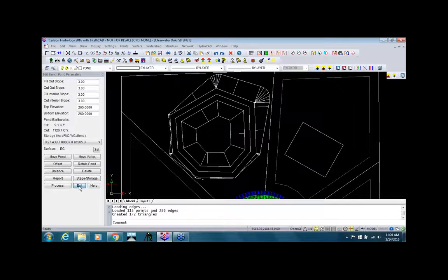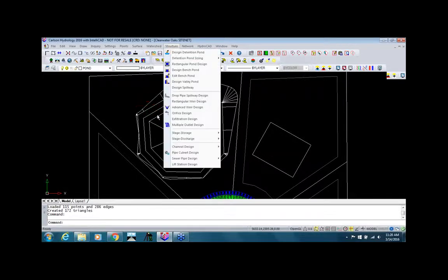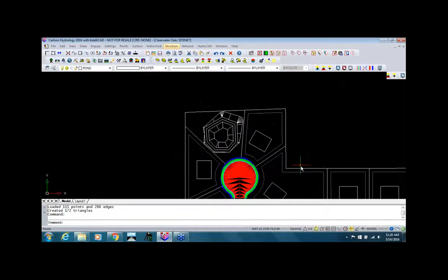So inside this menu here, you can also define the outfall structures. Maybe a weir coming out the side, off the back here, a multiple orifice outlet design. You might have a small diameter hole at the bottom of your outlet control structure with a larger one at the top, and ultimately a spillway at the top. All of that you can design inside this structure menu here.